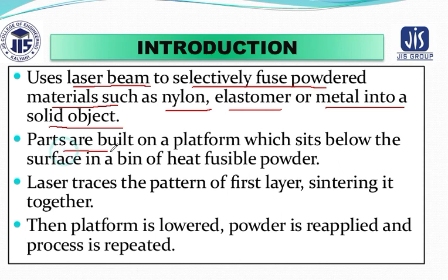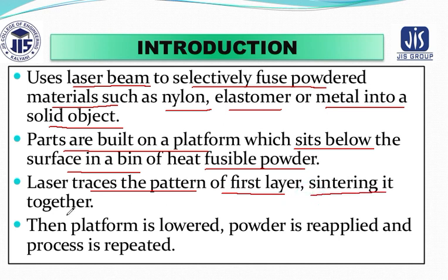Parts are built on a platform which sits just below the surface of a bed of heat-fusible powder. The laser traces the pattern of the first layer and sinters it together.